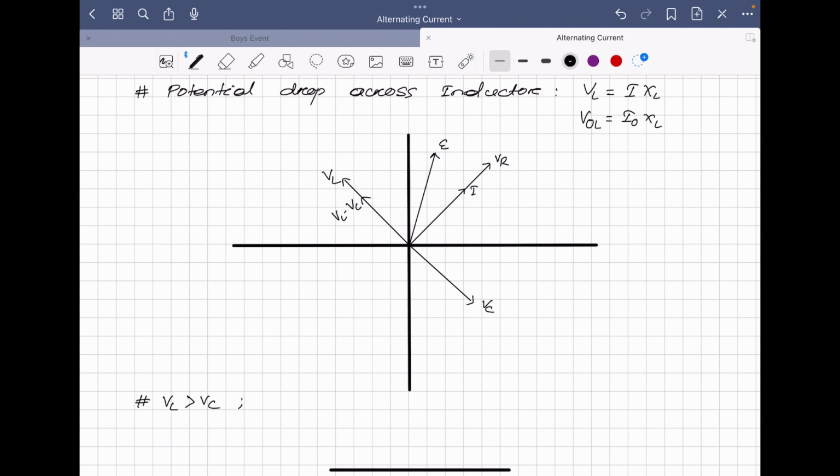So how can you find the impedance here? Here also you have to use the parallelogram formula. One vector is our VR and another vector is our VL minus VC, not only VL or not only VC. Here you assume VL is greater than VC, or you can assume VC is greater than VL also. If you assume VL is greater than VC, then our EMF leads current. If you assume VC is greater than VL, then our EMF is along this direction and that lags behind the current. Then how can you use the parallelogram law here?